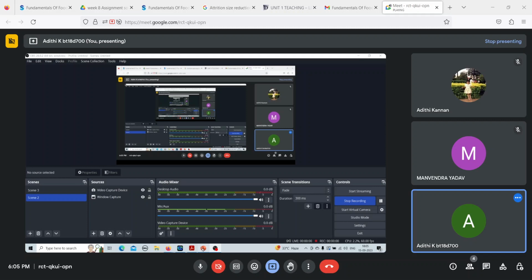But what we need to keep in mind is that the units of this Bond's constant are different. You have millimeters and you have tons. So make sure that the rest of the parameters are also unit-wise consistent. So M here is in tons per hour and power is in kilowatt. I am now substituting the values.